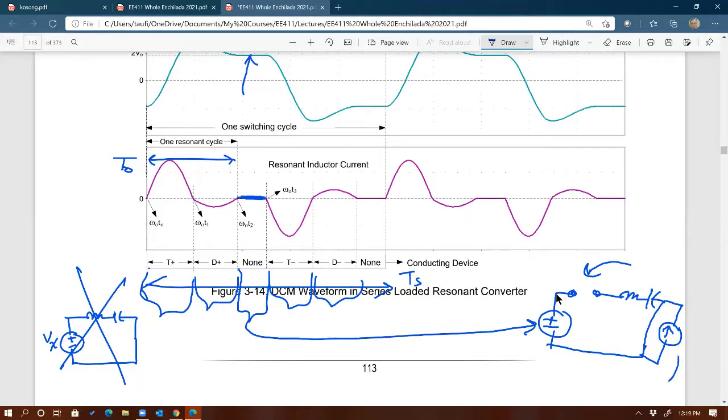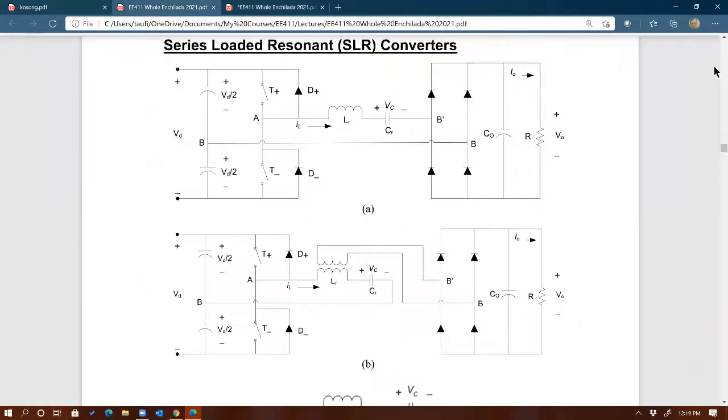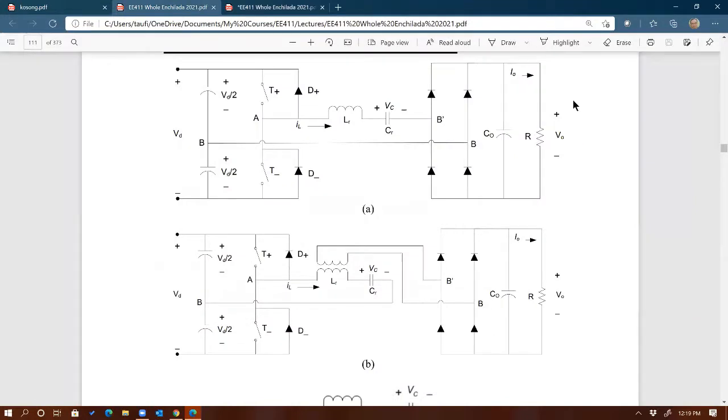So basically, this type of circuit, right? Because remember, this is a current source, right? So right here is basically constant current. You have regulated voltage divided by R, by Ohm's law, you're going to get I naught, right? And you have caps right there to maintain the output voltage.